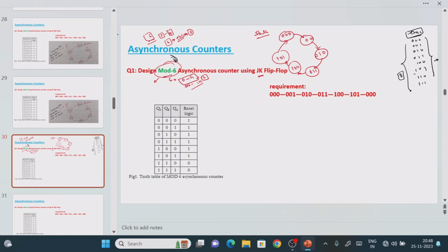It means that once 1 0 1 is completed, it should return back to the initial position. But the problem here is, as we are considering 3-bit information, as usual it will produce 8 possibilities, right? It means that it will produce 110 as well as 111 also. But these should not occur, yet if you take a 3-bit value, these also will occur. Now the question is, how do we avoid this? Then it will become the MOD-6 counter.